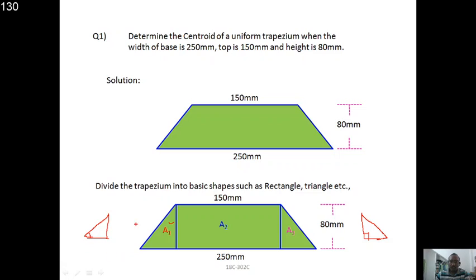And please also note that we should locate the origin. Generally, we want to place the entire object in the first quadrant. I already mentioned that please locate the total figure in the first quadrant. That is most important to get the solution. So in order to transfer the total object into the first quadrant, identify the bottommost line as the x-axis. So this is the bottommost line, and identify the leftmost part of the total object. So this is the leftmost portion, to give the y-axis. Now this entire figure has come into the first quadrant, right? So now this is our origin.